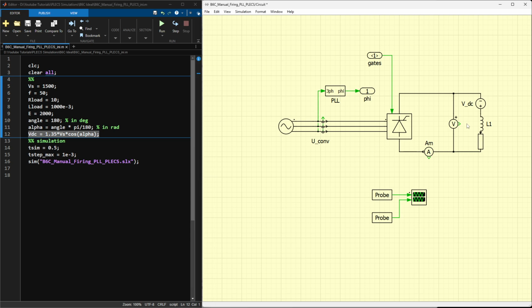What it means is that when the angle is greater than 90 degrees, the DC side source is now acting as the generator. Since the current cannot reverse due to the orientation of the thyristors, but the voltage can, the power is reversed. That means the DC side is now feeding power to the AC side.